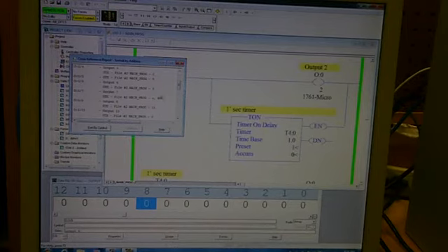It gets down to run 9 and turns it off. After I get to the end run of the program and I'm done running the program, then I write to my outputs. What do I write to my output? Well, I write out a 0. It's not on. So the logic that turns on an output has to be on one run.